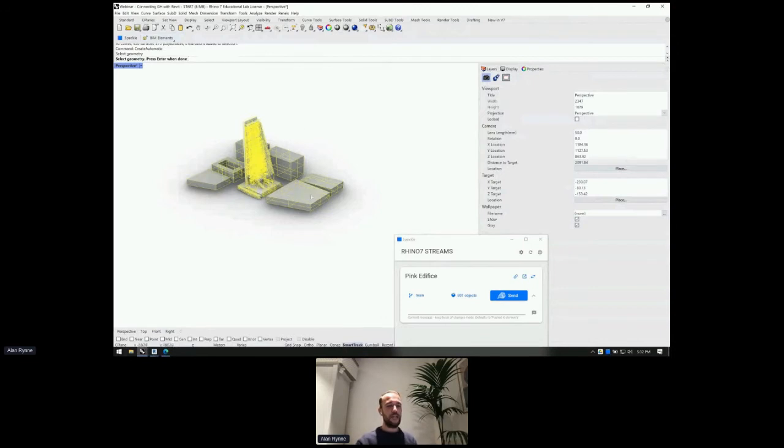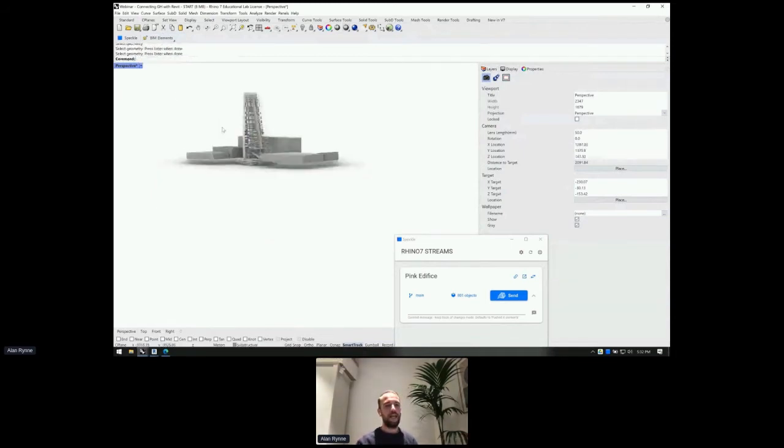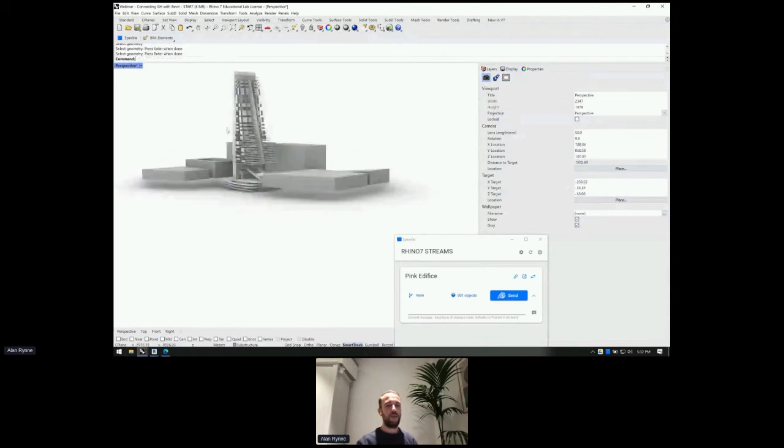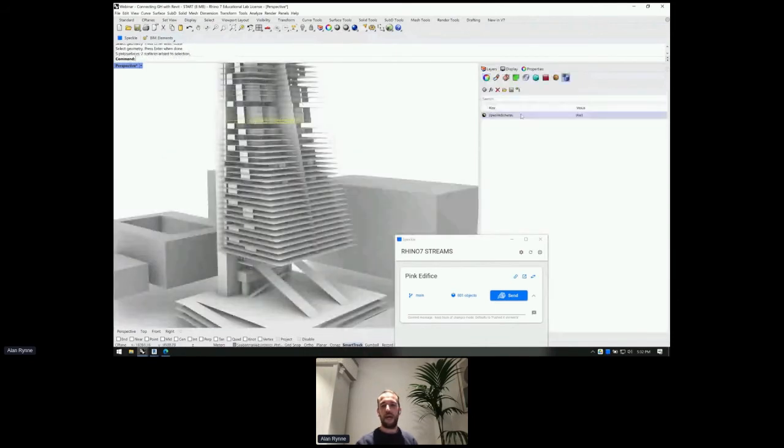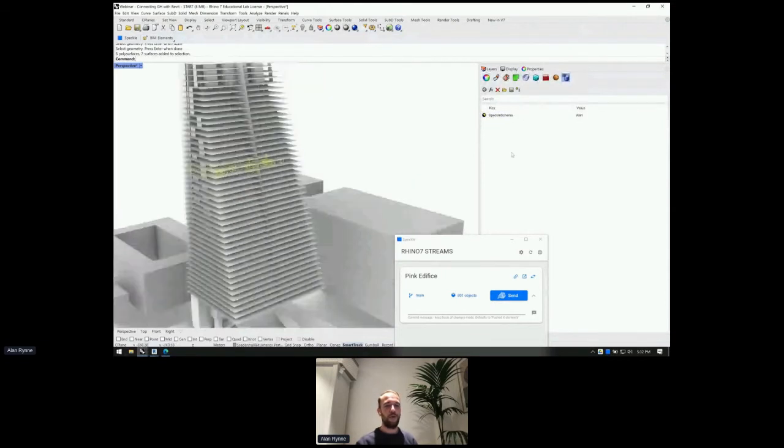And so we will see now that the Revit model, just by doing this operation, just pressing automatic, selecting all of our geometry, and letting Speckle do its thing. Now we have, if we select any random objects, like the inner walls of one of these levels, we will see that now all of these walls have the Speckle schema applied with the value of wall. So this will be sent along to Speckle, which I'm going to do right now.